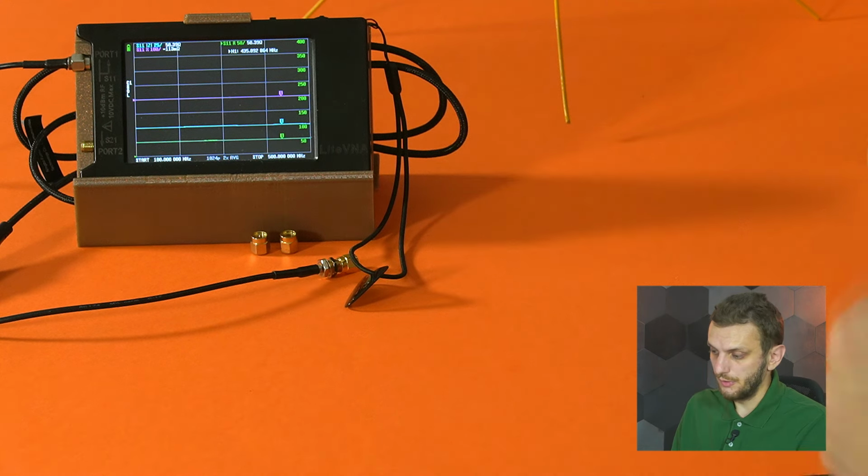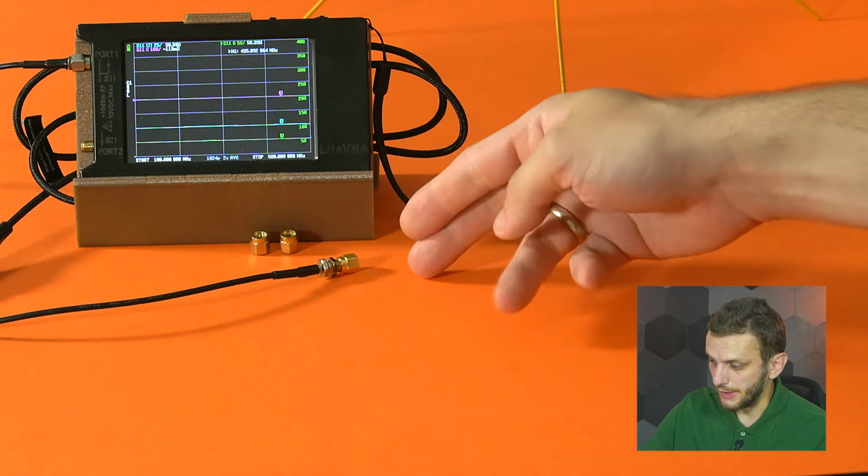Now, if you do have a practical antenna already built and you have a network analyzer lying around, you can always measure it. You can extract the S11 parameters and simulate that. I covered the method to use S11 parameters in LTSpice in more detail in a previous video. Now, if you do end up doing this, there are some measurement considerations to keep in mind just to get the best results. First, as with any good network measurement, the system needs to be calibrated.